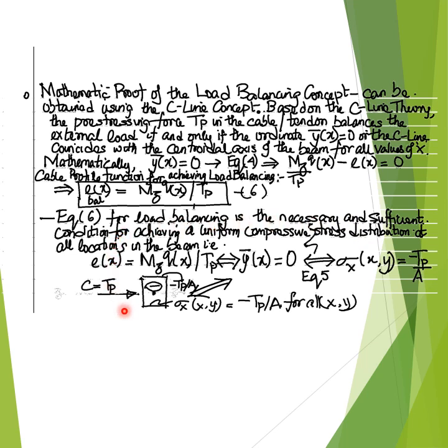And hence the pre-stressed concrete beam in which the load is balanced by satisfying the mathematical condition, that is y over bar as a function of x is 0 for all values of x, is in a state of pure axial compression and is free from bending stresses or bending moments.